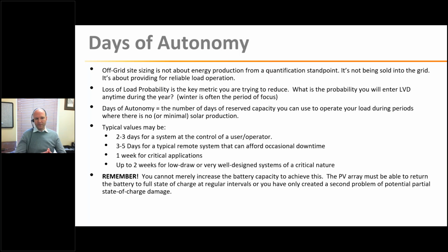So when we talk about how we size a system, days of autonomy is something that we repeatedly discuss with customers, and we provide a lot of OEM and application support for customers that are integrating our controller into another system. And when they do that, they will often ask about storage capabilities. So days of autonomy is defined as the amount of time that a system can actually run off its reserve capacity when you've got little or no solar production available.